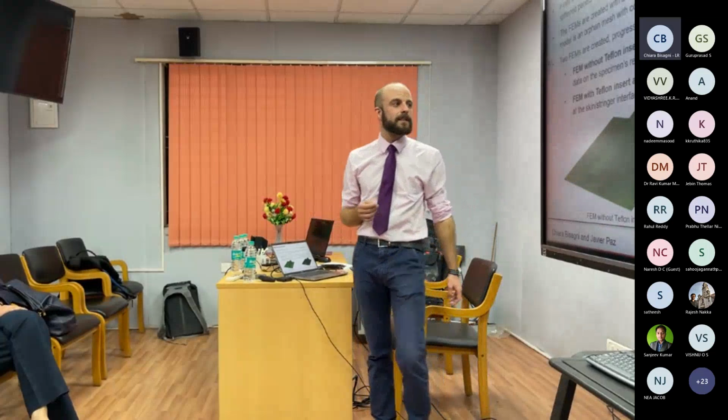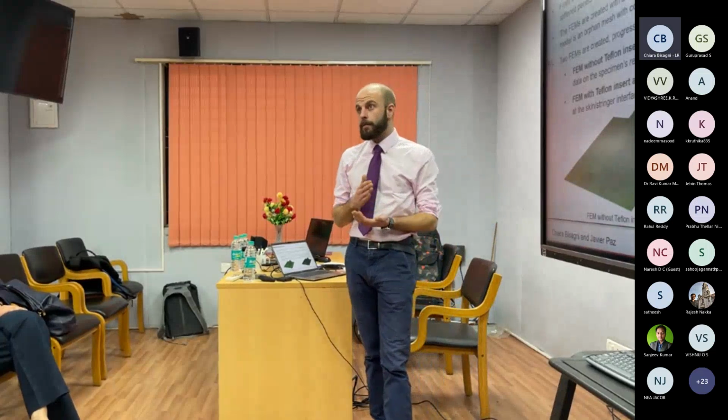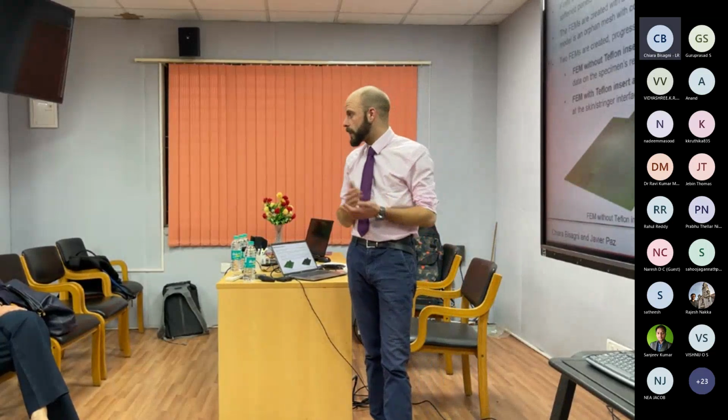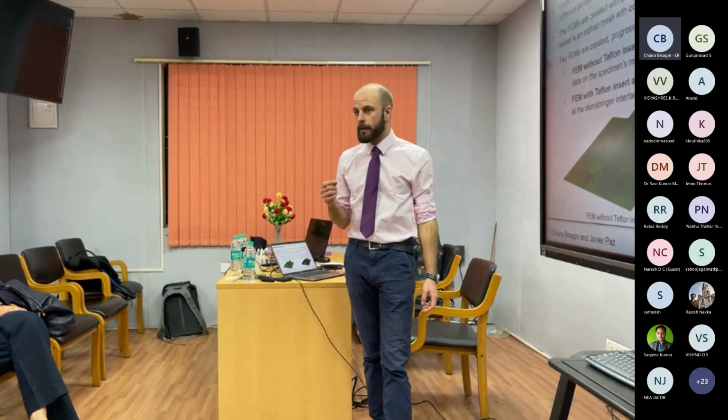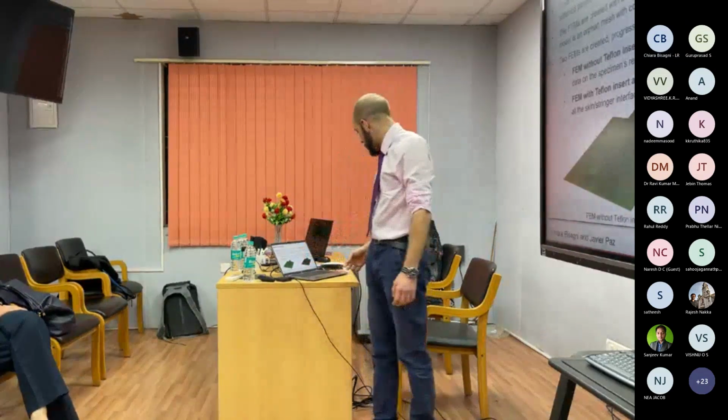Once we know that data, we refine the model. We make the mesh way finer, which is the one here. It's not that the specimen is black, it's that the element sizes are so small that you just see the lines, you don't see the elements. That's the one that we'll first check against the previous model to confirm we're getting the results we expect, and then we can understand how the delamination will begin to propagate, how it does, and how the components behave.